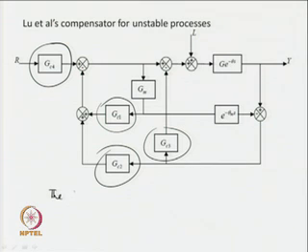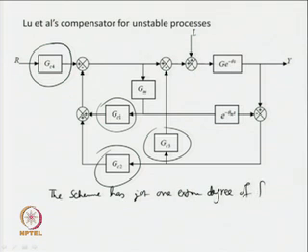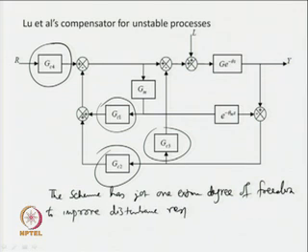Now, the control scheme has one extra degree of freedom to improve particularly the disturbance response. So, the disturbance response can be improved significantly with the help of appropriate tuning of the controllers.